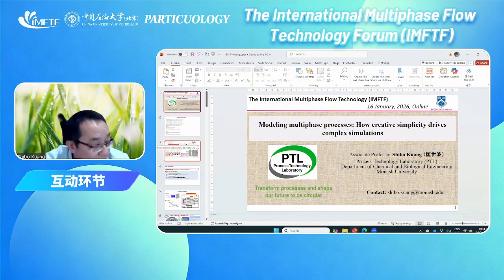One example is our drag force formulation for Herschel-Bulkley flow. If we follow a standard procedure, we have to go through a 3-year project to formulate a drag force model. It's almost repeating our previous PhD project. I think that's impossible. However, in our study, we found if you simply combine two modeling efforts, you can realize a reasonable simulation.